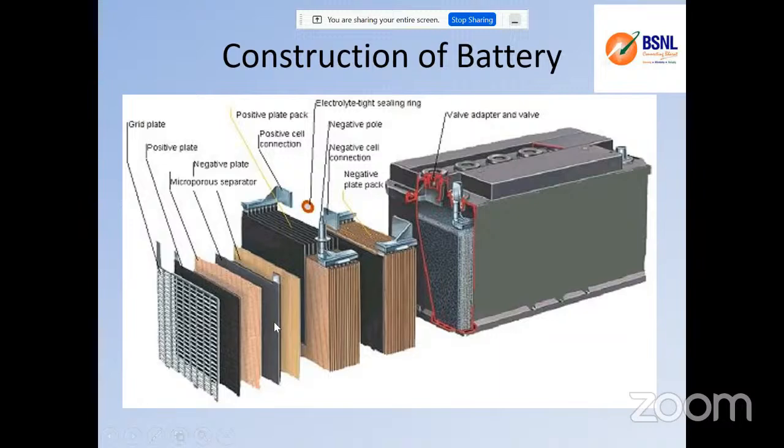Like that, they will be aligned together to make a complete block, and this block will be filled again. Even though it is a 12-volt battery, inside it will have only a small portion, which means the cells are connected in series of 2 volts. Normally the primary cell they used to say is either 1.5 or 2 volts only. Then the 12 volts is arranged with 6 numbers of 2-volt cells built together in the container. So this is how the container and construction of the battery look.